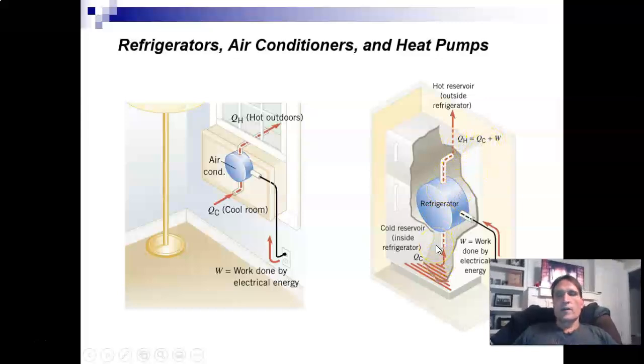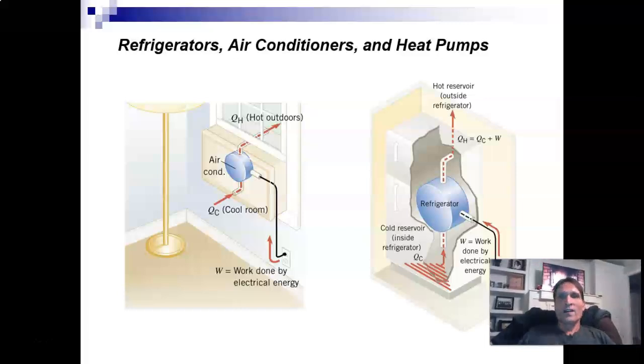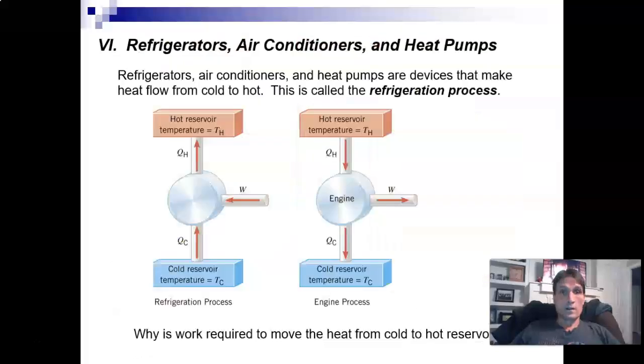So if you leave the door open inside your refrigerator, you will remove a little bit of heat from the inside of the refrigerator, but you'll exhaust even more of it out into the room. And so the net effect is that you will warm the room. The temperature will rise even more than if you did not do this harebrained idea. So don't leave refrigerator doors open in the summer to cool your kitchen. It's just a bad idea. It violates the second law of thermodynamics. So the answer is no.